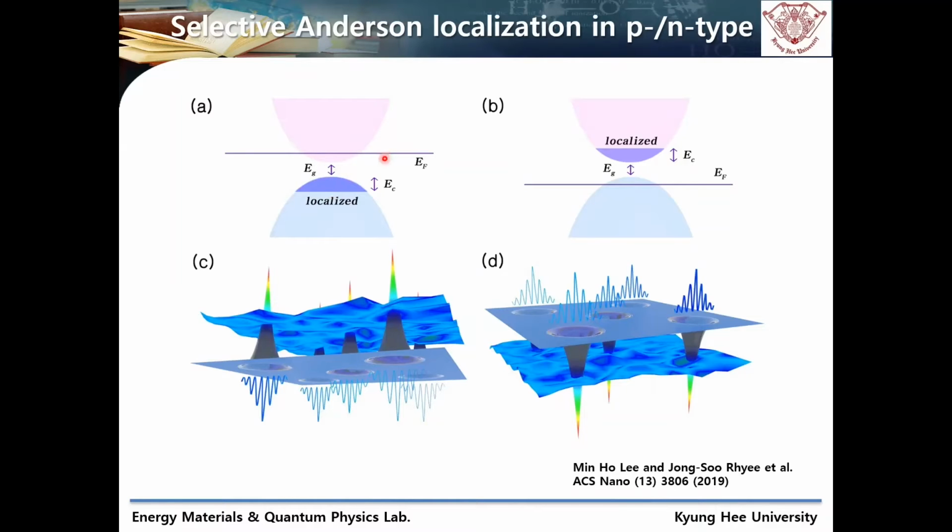In the case where the Fermi level resides at the bottom of the conduction band, it is an n-type material, but because it is a narrow gap semiconductor, basically hole excitation can be generated and decreases the negative Seebeck coefficient. But when the hole is blocked by strong localization of the hole, the effective energy band gap increases.